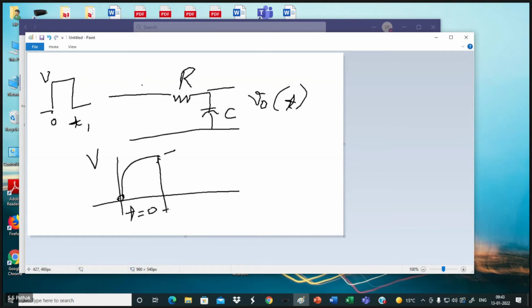That is the voltage here. After that, what happens? This capacitor will start discharging because the pulse is gone now. The capacitor starts discharging and it goes according to the same time constant like this. Your T2 might be somewhere here, or T1 might be somewhere here. You can adjust like that.